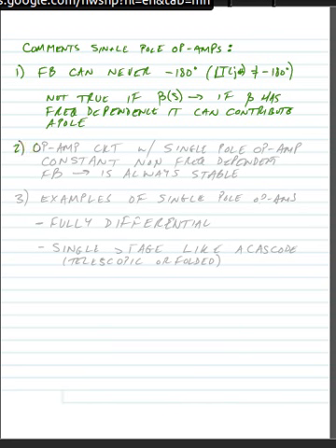Now, our second thing is an op amp circuit with a single pole op amp and constant non-frequency dependent feedback is always stable. So we don't have to worry about ringing or oscillation.